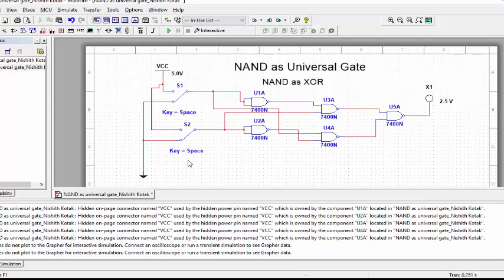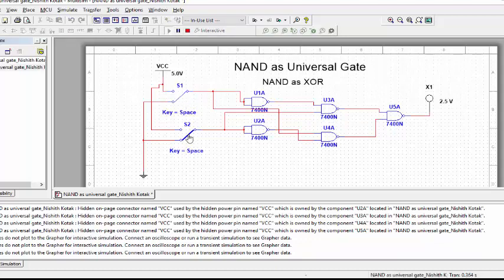This is the circuit that resembles the equation that we have obtained. Here initially both the inputs are connected to the ground, that is logically low. Thereby the probe indication is 0. Whenever I connect one of the switches to VCC, that is logically high, my probe would go logically high. And if I connect both the inputs to VCC, my probe would again turn off, which is the concept of XOR, which is the inequality detector.